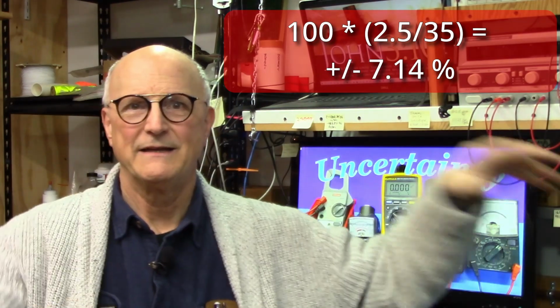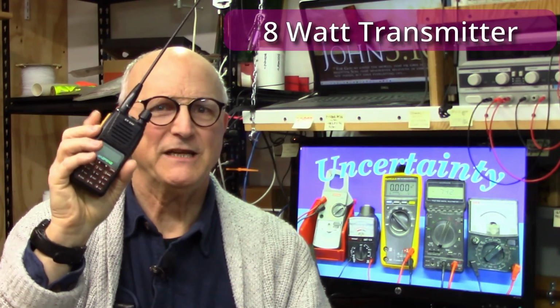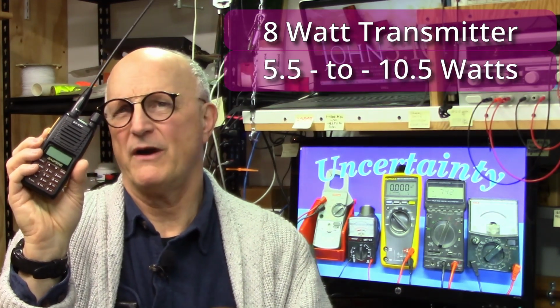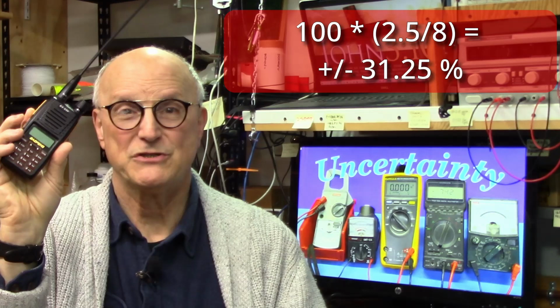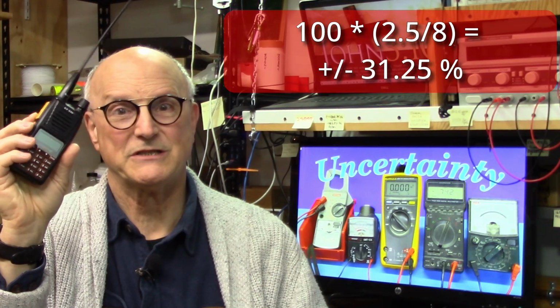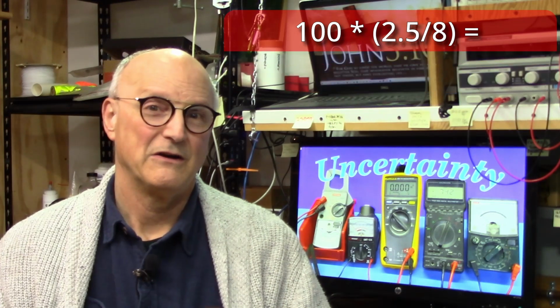Now suppose this is the only element that we have for this frequency, and I'm trying to measure the output power of an 8 watt handheld transceiver. If that HT is actually outputting 8 watts, then my Bird might report anything from 5.5 to 10.5 watts. Now, 100 times 2.5 all divided by 8 gives us an accuracy of plus or minus 31.25%. All of a sudden, this doesn't look so wonderful, does it?